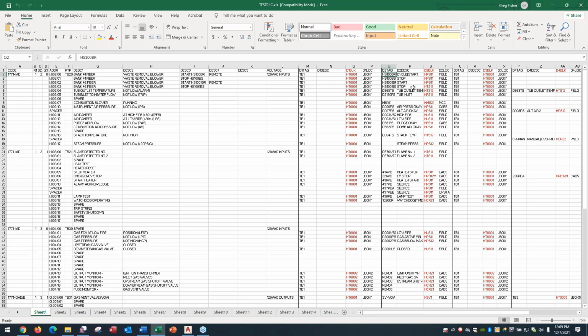So you put the tag of the component down, you put the description down. In the description, you know how there's 3 lines of descriptions you can use for any individual symbol when you place it down. What separates the descriptions is your pipe symbol on your keyboard. That's why it says cycle pipe start. When it actually creates the drawing, you're going to see that description line 1 is going to be cycle, description line 2 is going to be start.